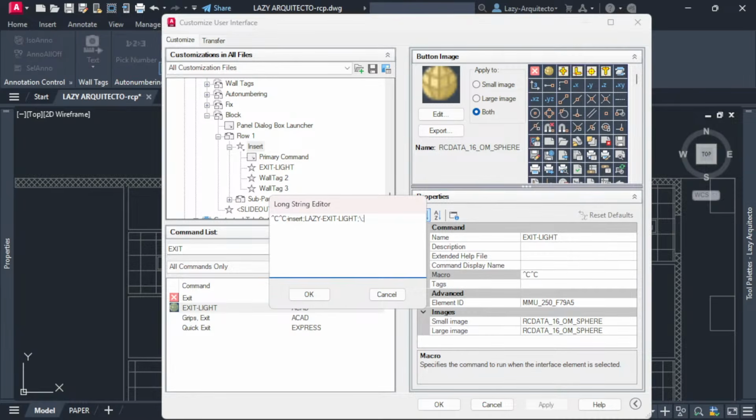We're gonna go back to the scale in a moment, but after that, AutoCAD is gonna ask me for the rotation of my block, and usually gives you 0. So I'm gonna press enter for now to accept that 0. We're gonna have to go back again to the rotation. We're gonna customize those two things, scale, rotation, and so on.